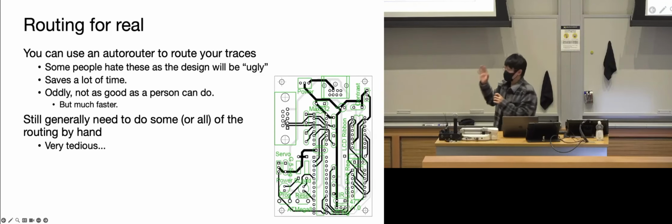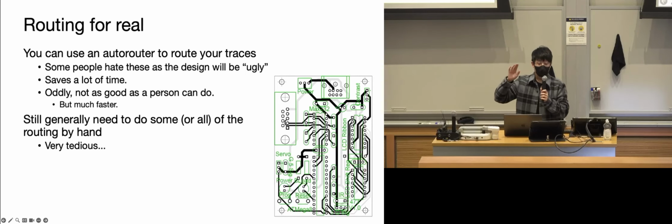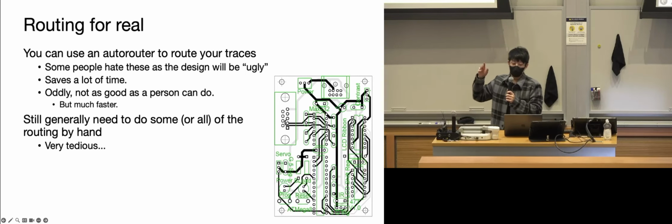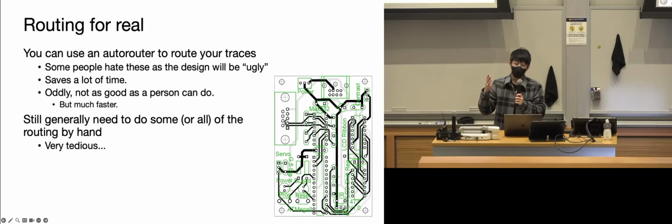And then you will, based on that, do your routing. Whenever you add another wire connected on your board, that air wire will just disappear, so that you always know how much percentage you have achieved, etc.